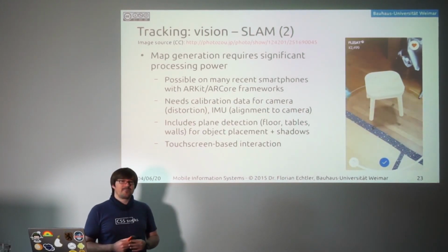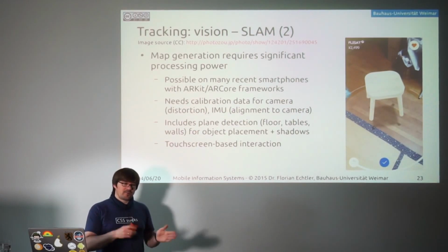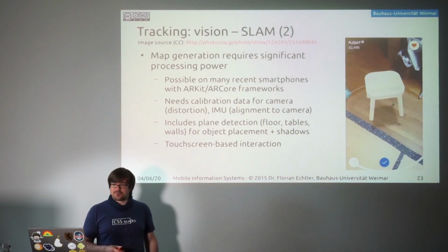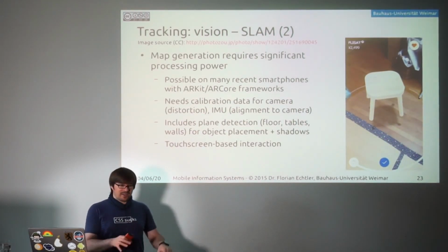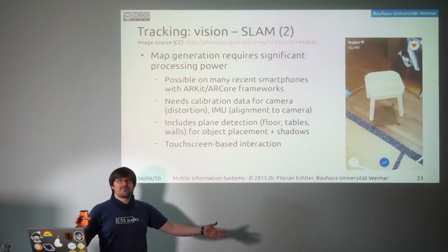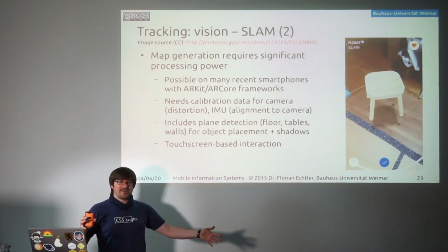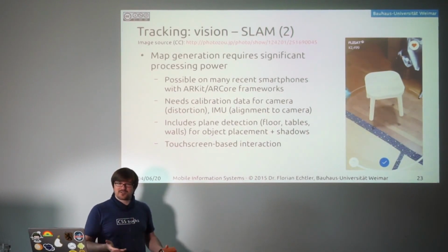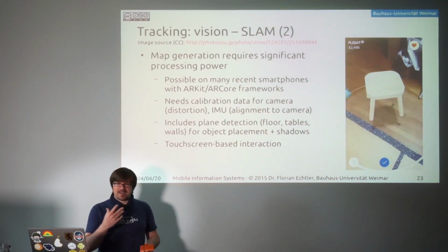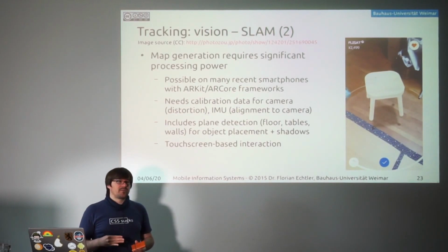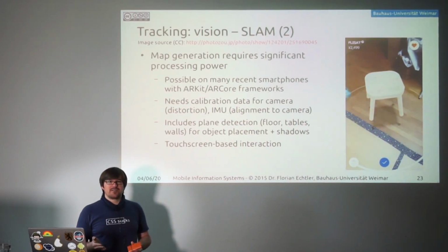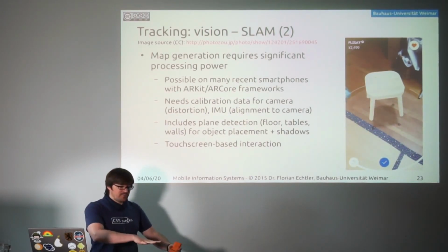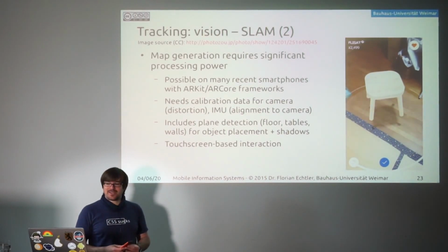And one important feature both of these frameworks bring along is so-called plane detection. As I already mentioned, they create a 3D point cloud of the environment, but this point cloud doesn't yet have any kind of semantic information. So you just have a number of 3D points that are objects around you. And this plane detection approach usually uses an algorithm called RANSAC to detect larger flat areas within that environment.